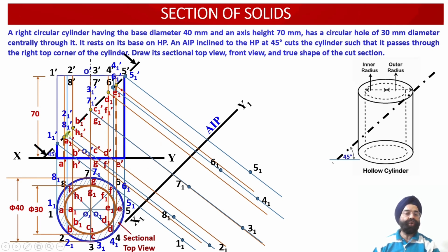So now onto these orange projector lines, 8 points A1, B1, C1, D1, E1, F1, G1, H1, they have to be evaluated onto the auxiliary plan projection view. Now first point available with us is A1. We'll measure the distance of point A1 from the XY reference line.